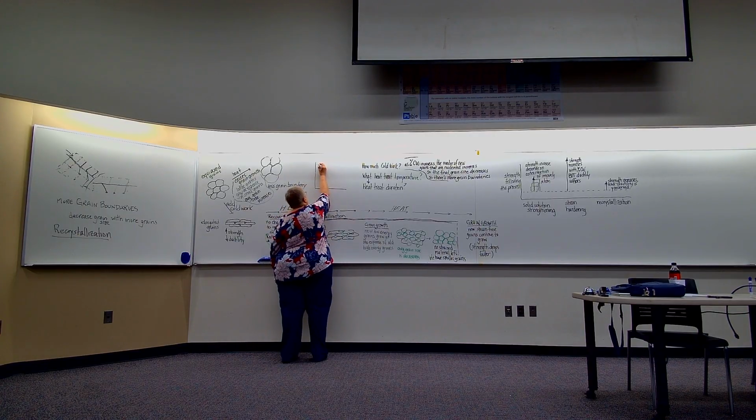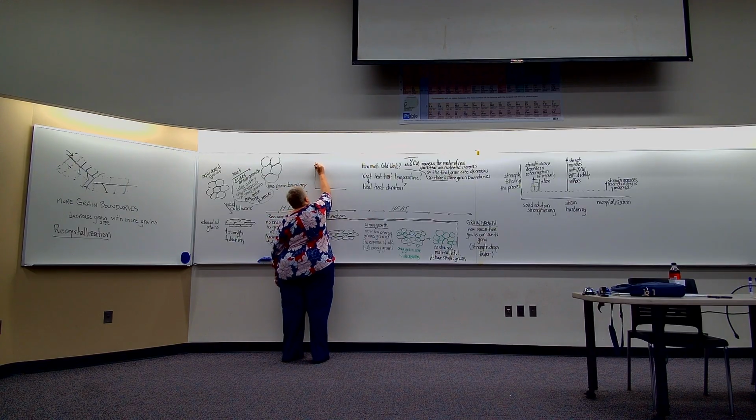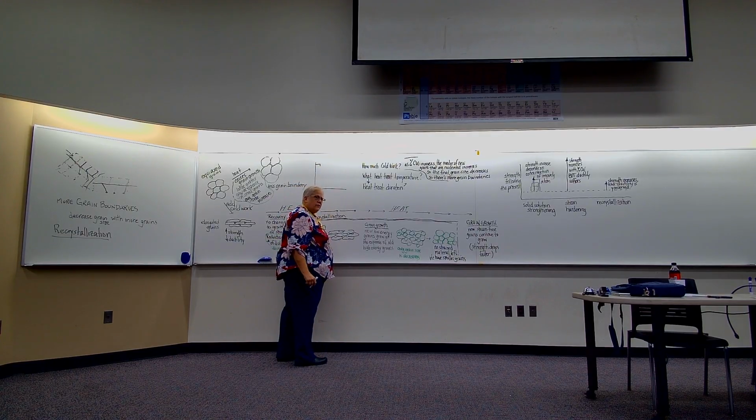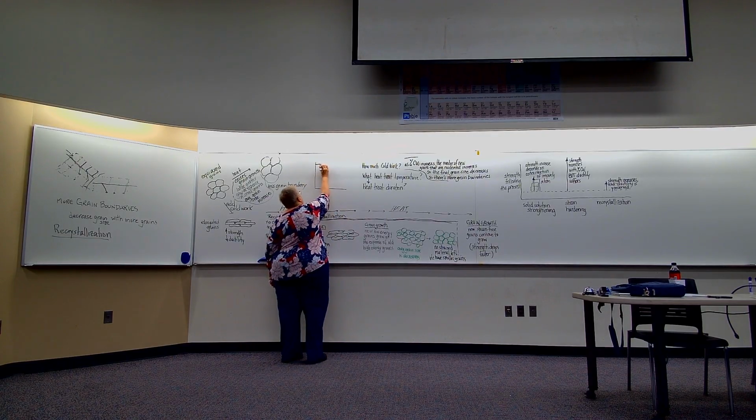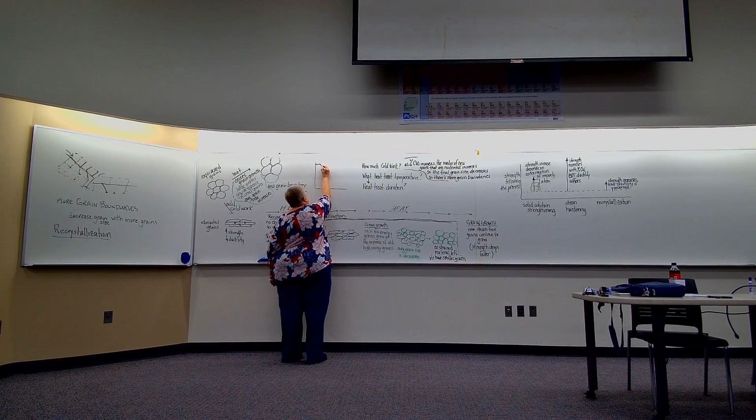Recovery, there's going to be a reasonably noticeable drop in hardness. Let's call it this. That's recovery. And maybe it doesn't happen in 1 second. And then during recrystallization, it's going to stay relatively constant, but it will drop during recrystallization.